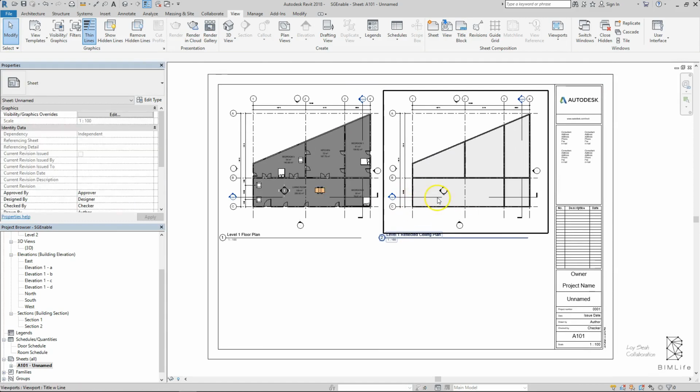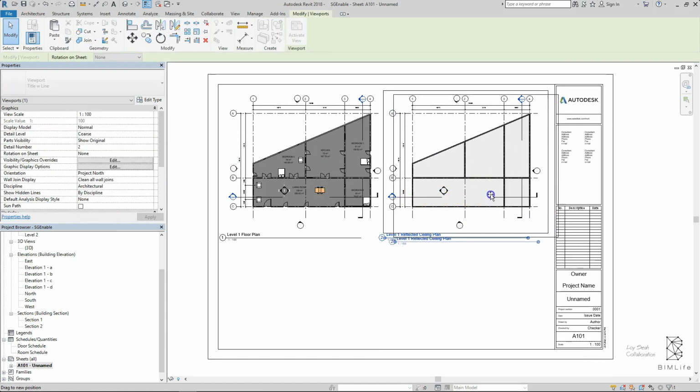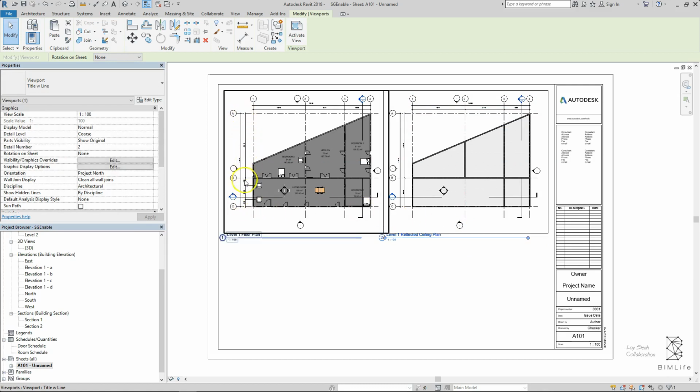While you place views in your sheets, make sure that they are aligned. You can simply drag your views through a left click and hold. Make sure you see a blue dotted line before you release your mouse to ensure that both views are synchronized either in the X or Y axis. You can see my grids A, B, and C run directly on the same Y axis throughout these sheets.